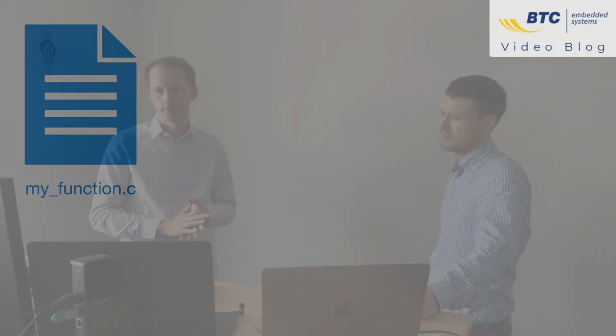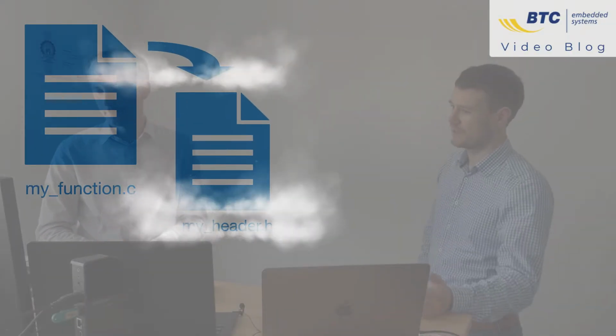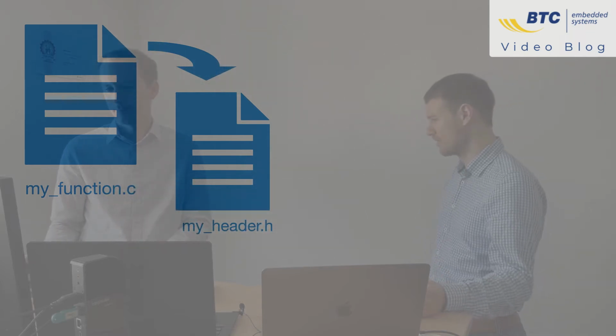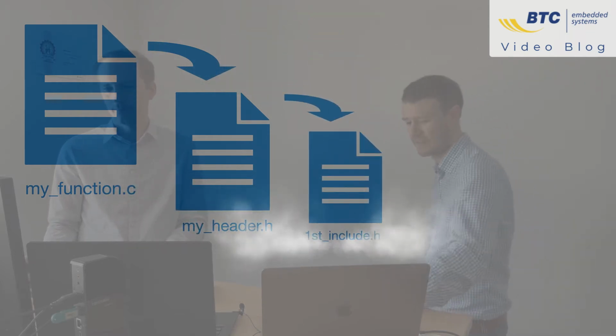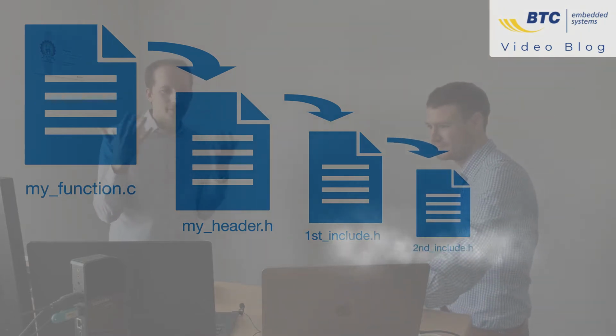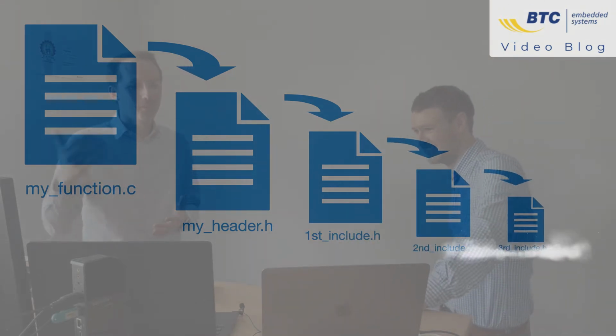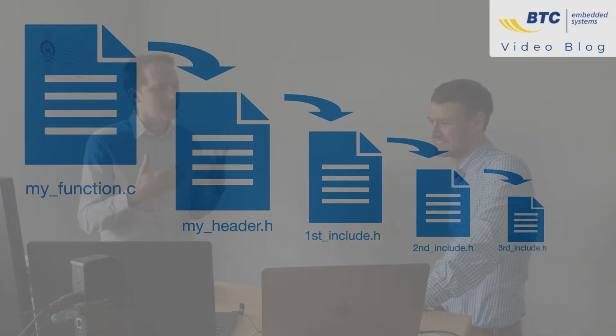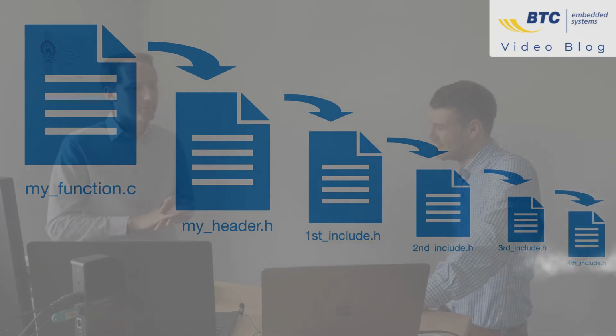Okay, but these external headers often have other includes, and we've seen projects where the include chain can really contain dozens of folders, hundreds of files, and things like that. So right, and in many cases, if we get to the fifth and sixth level of includes, we often end up with files that belong to a target and they're not compilable on the PC for the simulation. True.